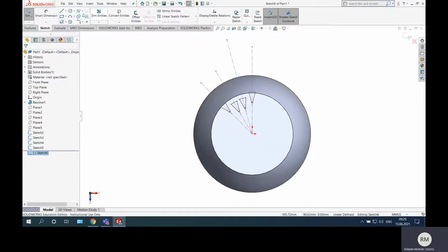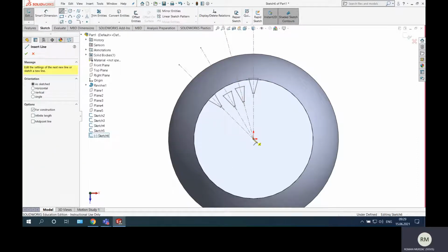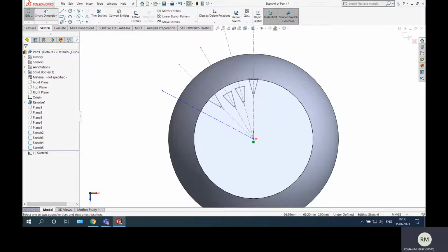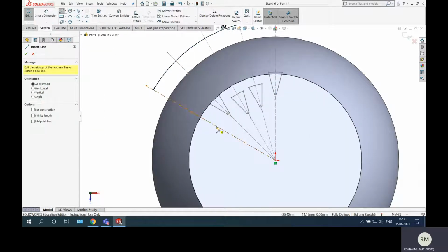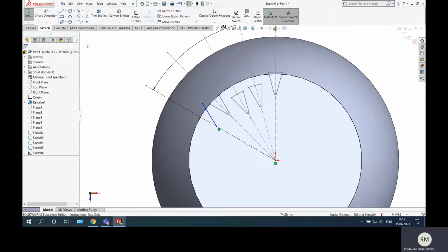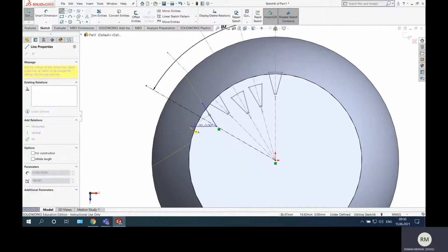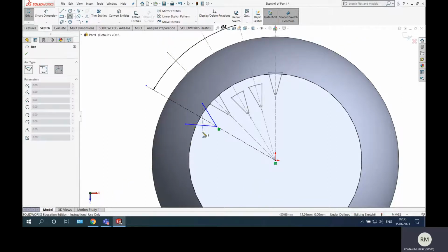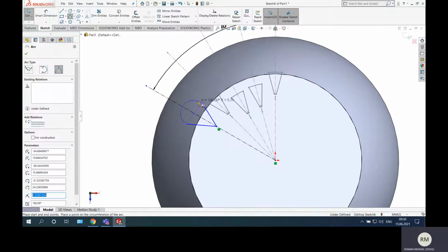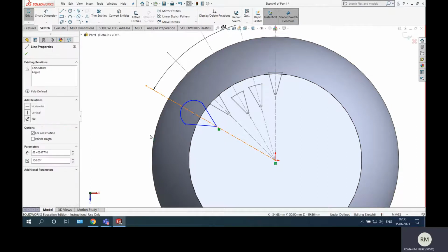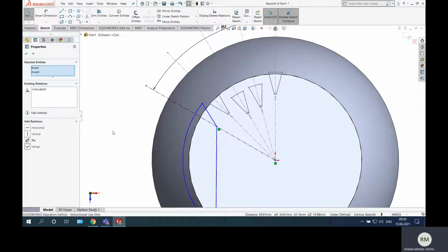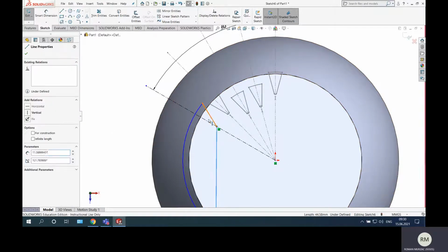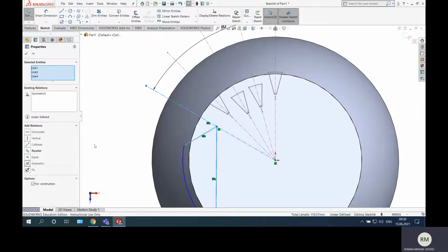Look perpendicular to it. Create again the axis, and now it will be 60 degrees. So from here to here will be 60 degrees. And same profile. Again, repeat same operations: 2 lines, 1 arc, and the rest of constraints. So I create my elements and just start now. This point with axis should be coincident, and also this point with center to be merged, and this line with this line from the axis should be symmetrical.